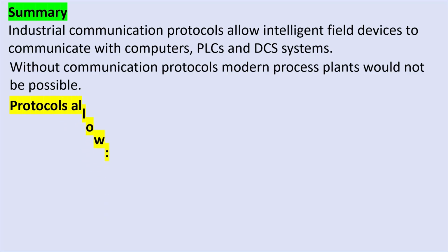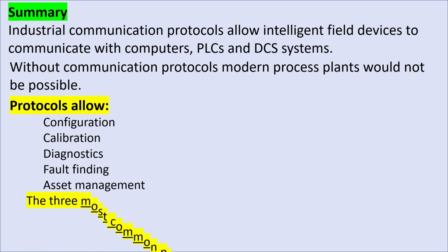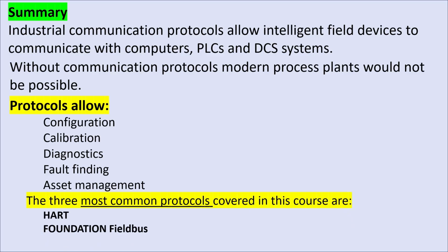Protocols allow configuration, calibration, diagnostics, fault finding, asset management. The three most common protocols covered in this course are HART, Foundation Fieldbus, and PROFIBUS.